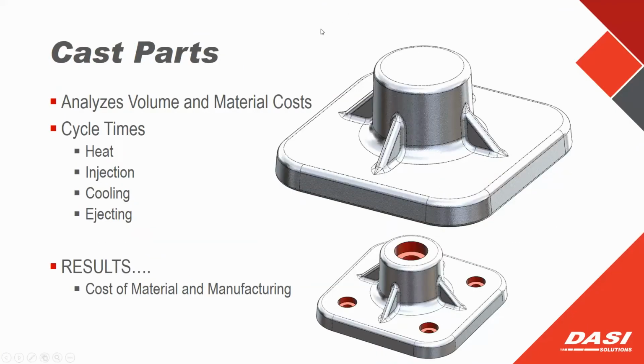Now for cast parts, this one here is interesting. What it's really doing is more like a plastic injection mold circumstance. It's analyzing the amount of material that you're using, so the cost per volume on the material is all equated to the physical volume of the part. There are, however, other inputs. Those have to do with the cycle time specifically with this part: the amount of time it takes to heat the mold, to inject, or to fill, both of those are kind of used synonymously together, the cooling wait time, and then the removal from the mold, or the ejecting process. What you're really getting is the cost of materials plus that manufacturing time.